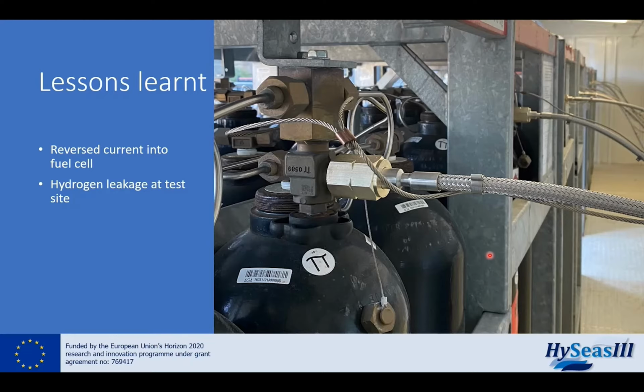This was clearly a new event for the emergency units, and a lot of questions were raised during the event. Two of the firemen went into the hydrogen container and managed to close the leakage. In a summary meeting after the incident, the fire department classified this as non-dramatic. It turned out that the leakage was due to a human error. The connection valve was not tightened properly after replacement of a package.